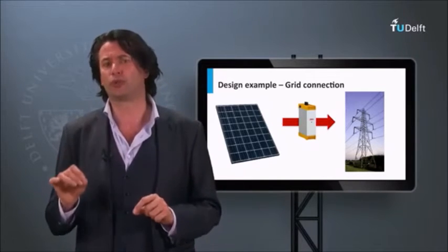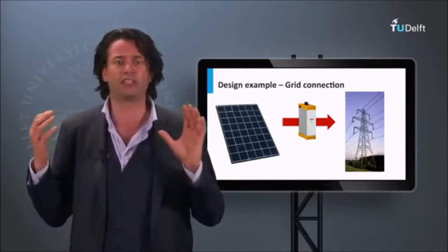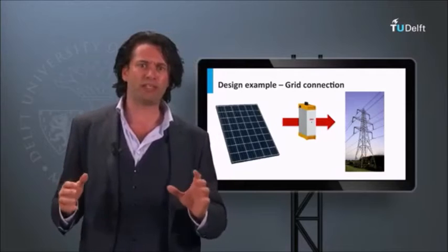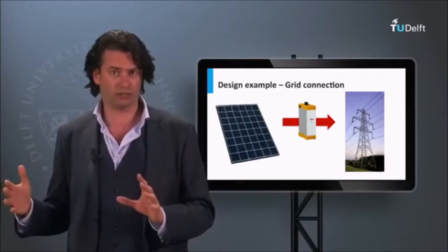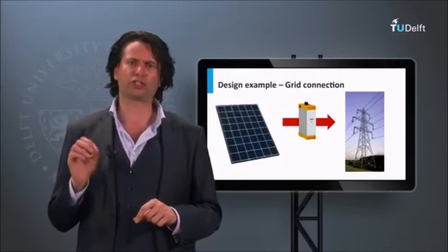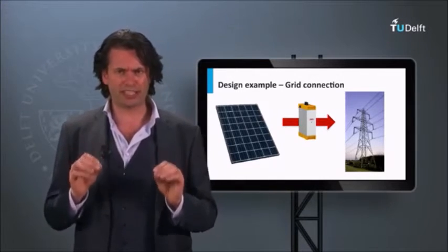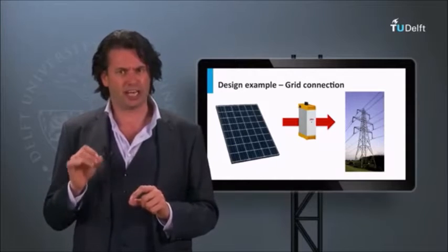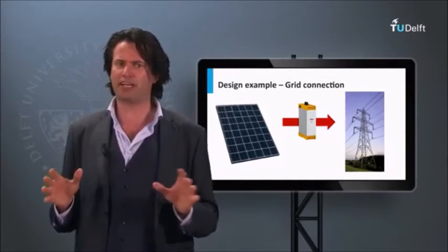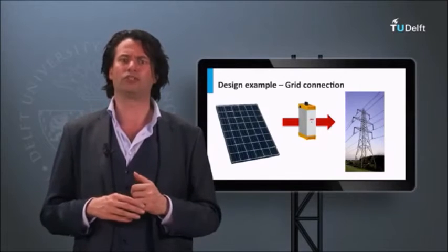This was not true for the standalone system, as any surplus or deficit of power had to be met with a variation in the storage size, leading to considerable system costs. Consequently, in grid-connected PV system, it is usually seen that the inverter is sized based on the PV array sizes and not the load size, like in the standalone systems.